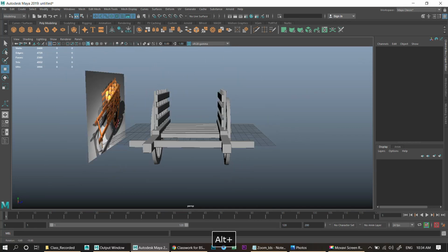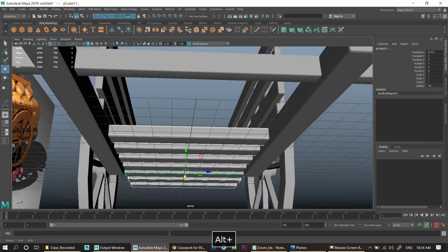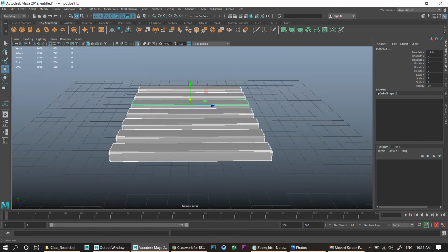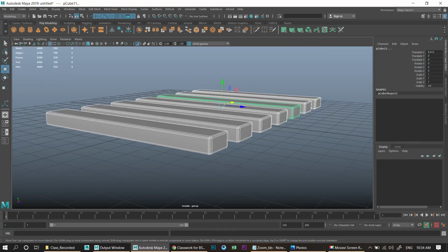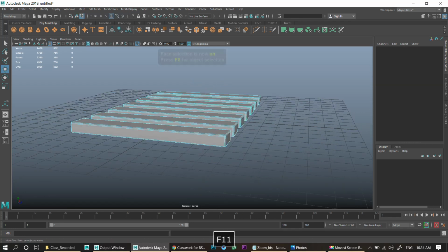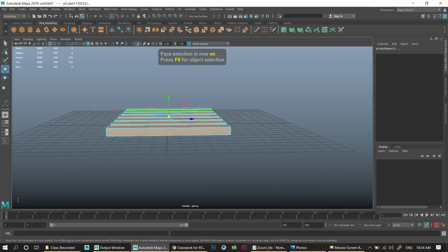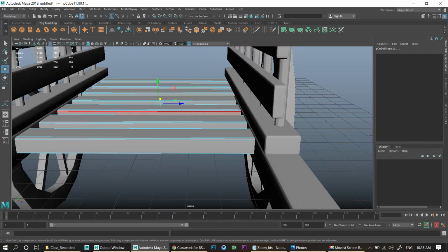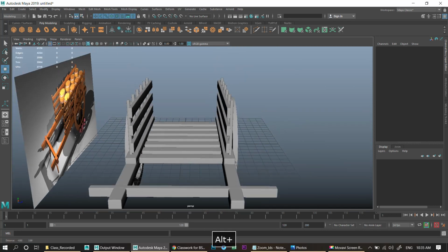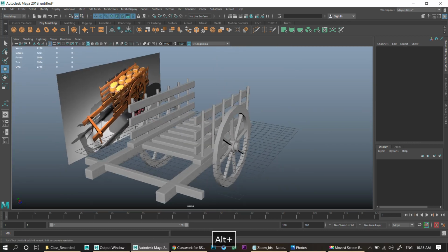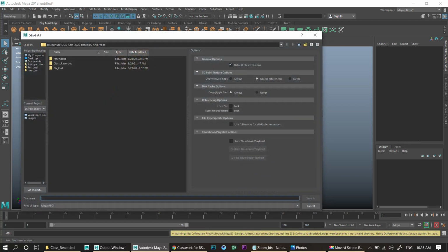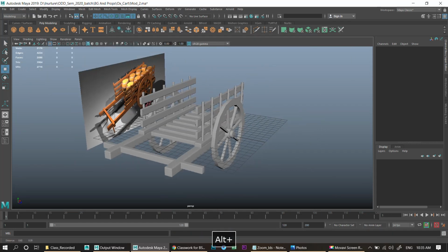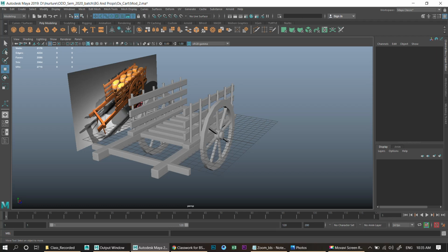This is enough. And even for this, these are all extra faces. You can delete them. Okay, press F11, so you can go to face mode, select all and deselect this one. Only this will be left over. So anyhow, it's all hidden. You can delete, okay, for more optimization, so that your poly count will be reduced. Fine, is that clear? Okay. I hope this is clear.